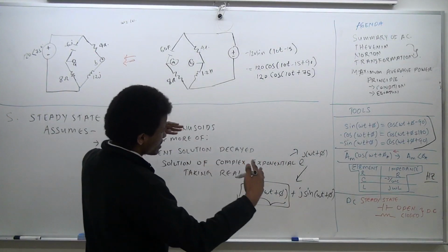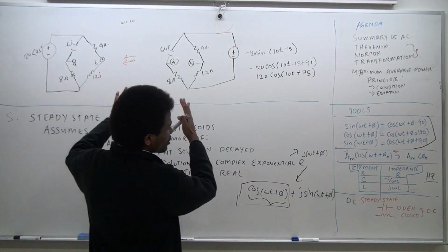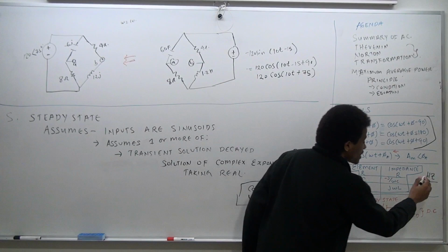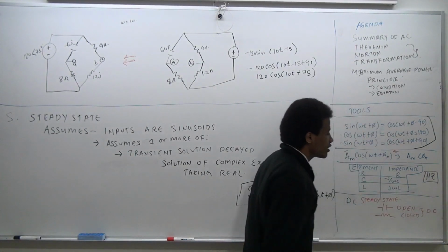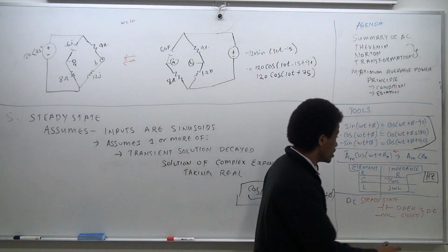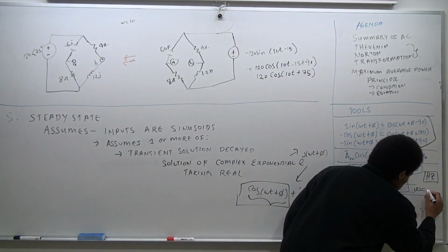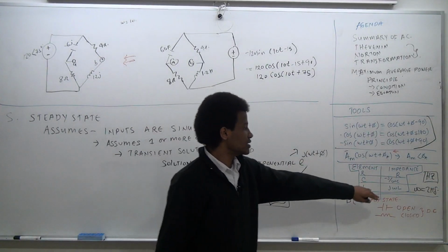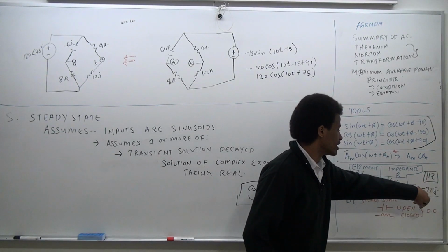And usually that's the first step. Or they can tell you to find maybe a voltage or a current in a circuit. But you can't do anything unless you know the angular frequency. But if they give you something in terms of hertz, you know you're not dealing with angular frequency. This is just a regular frequency. So you have to convert it to an angular frequency using 2 pi f. Very easy. So just use the formula and you'll get something in angular frequency.